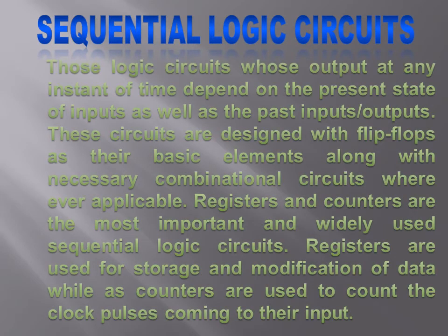Sequential logic circuits are those logic circuits whose output at any instant of time depends on the present state of inputs as well as the past outputs. These circuits are designed with flip-flops as their basic elements, along with necessary combinational circuits wherever applicable.